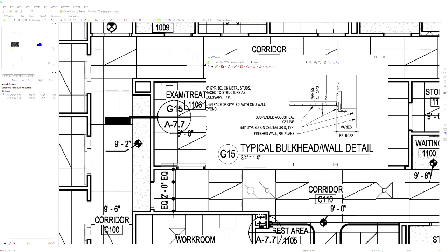If we're standing here and looking this way, we would look up, we would see these ceilings right here at 9'6", and it's showing the wires for the suspended ceiling system. Then you have gypsum board on a ceiling grid. So gypsum board, drywall in other words, and you see it there as indicated. What you can't see is this little transition, but that's how you look at those details.